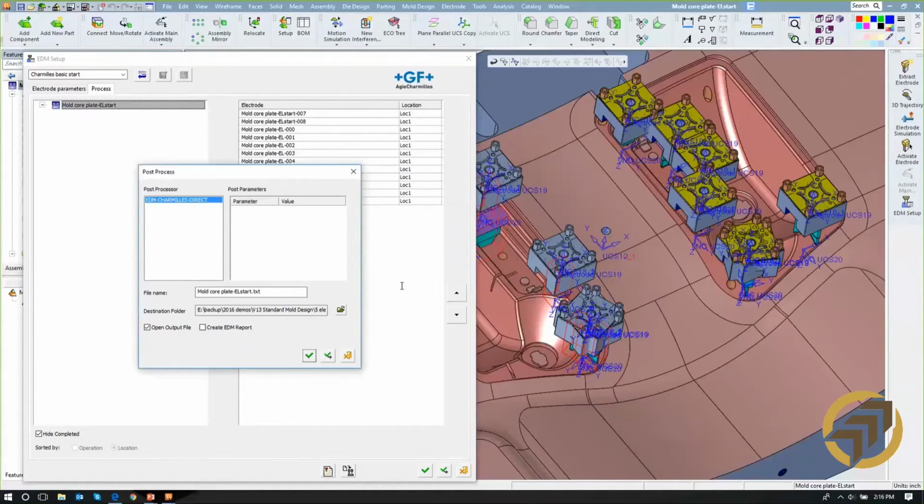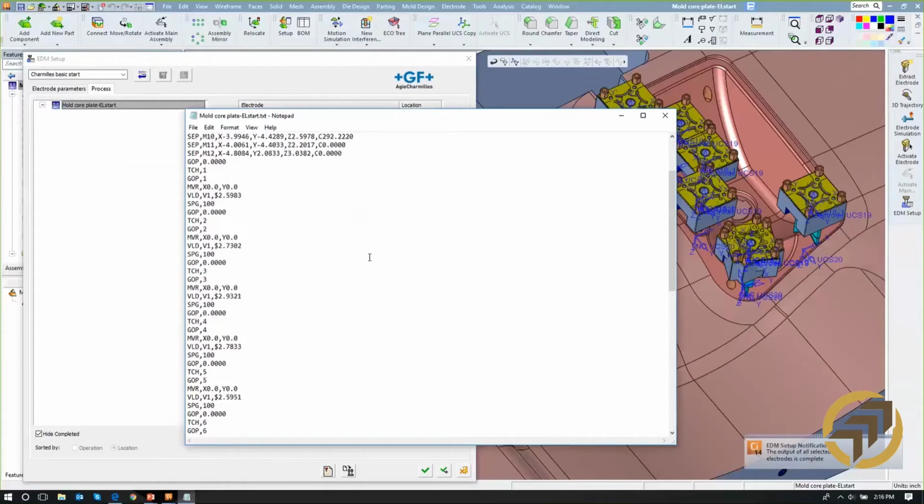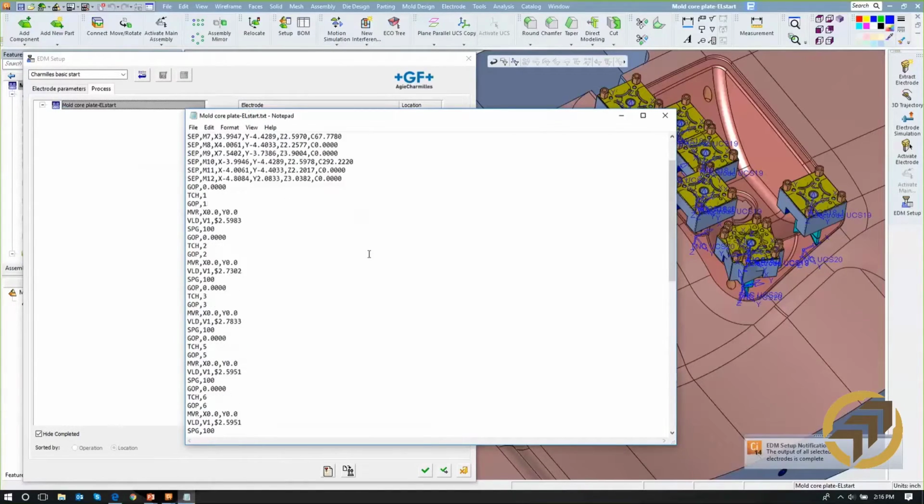So basically it's going to give me the code that I need to program my machine. Now, this is very, very important to think about because, late on a Friday and I'm rushing to program my machine, I might come in here and put in Y positive 1.5 or Y negative 1.5374 instead of the actual number that you see me with the cursor over.